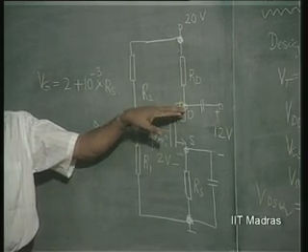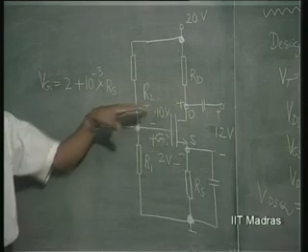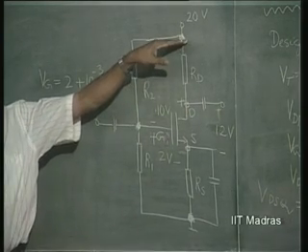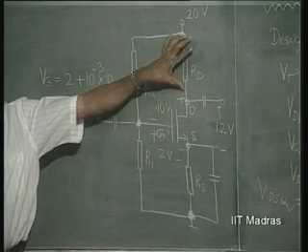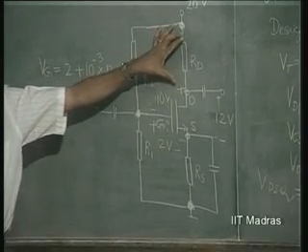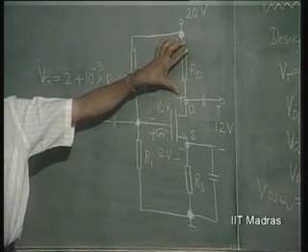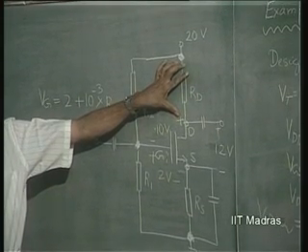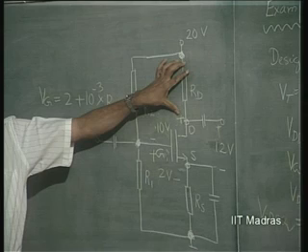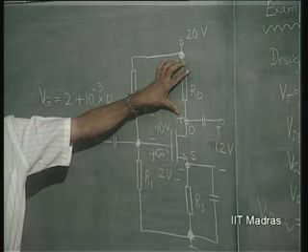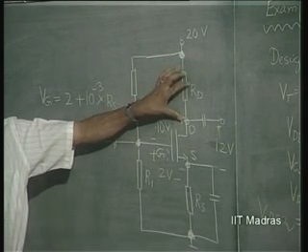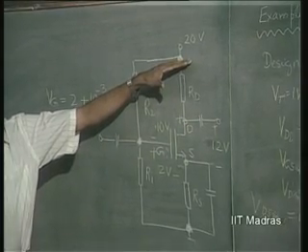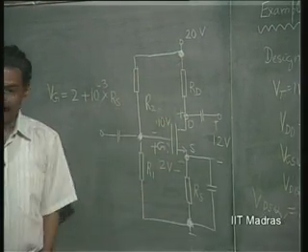So, above this Vg we must have further 10 volts, rest of it only has to be given to Rd. Now, why I am emphasizing on Rd is Rd should be made pretty large, strictly speaking, in order to make the voltage gain, which is Gm into Rd into Rds divided by Rd plus Rds. So, if our voltage gain has to be made very large, we have to have Rd as large as possible, compatible with this idea.